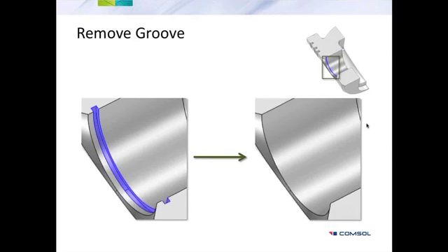The same way you would be able to select the groove where this retainer ring was sitting for the pin. Of course, when you remove it, you fill it up with material, and it's the same thing as if the ring would be there, although you have a lot less details in your geometry now.